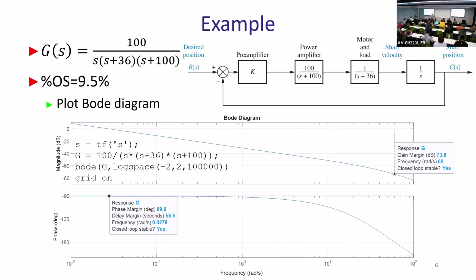So these are where these numbers are coming from, and you will lose stability exactly when your Nyquist plot crosses the -1 point on the real axis. This is exactly the boundary condition: here it's stable, crossing that point it's unstable, because the number of encirclements will change at that point. So this is exactly where you measure gain margin and phase margin. All right?